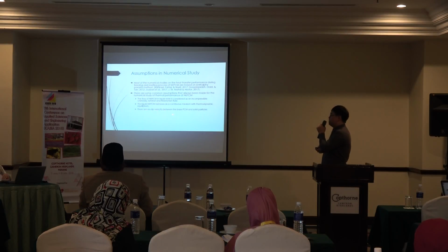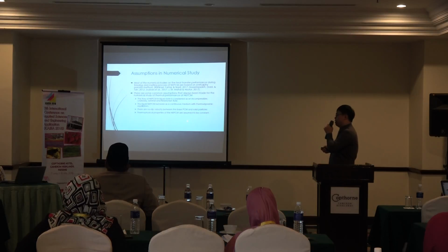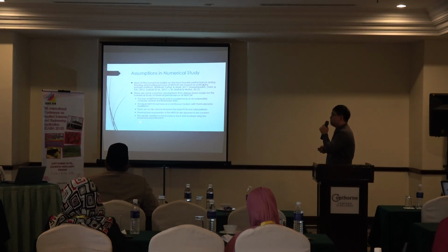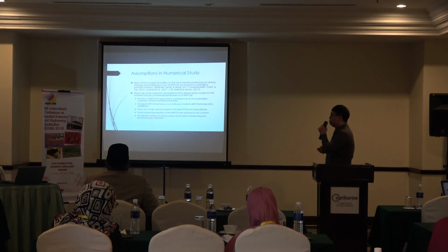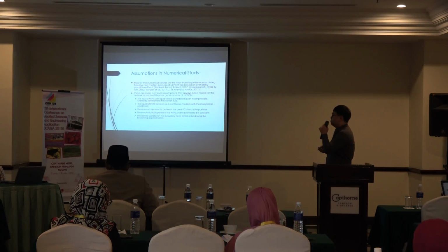There is no slip velocity between the base PCM and the nanoparticles, and the thermophysical properties of the PCM are assumed to be constant, where the density in the buoyancy force term is solved using the Boussinesq approximation.